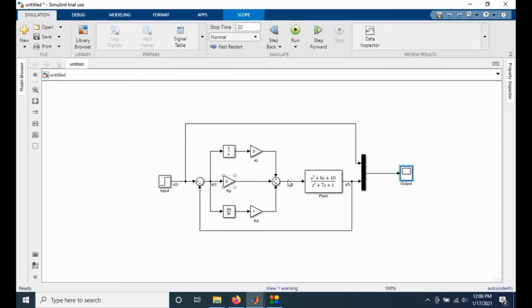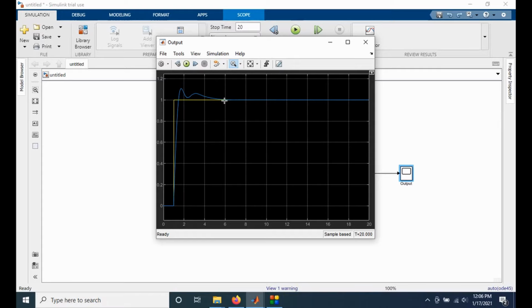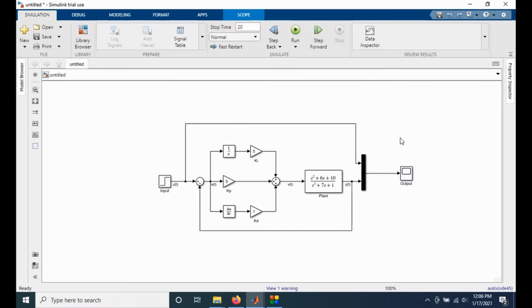We're going to deal with it in a slightly different way because it's related to the final step of controller design. At this point, we have tuned Kp, Ki, and Kd, and we have verified that our output is within some sufficient parameters. What we have not done yet is verified whether the input into the plant is achievable. Let's create a new scope and call it TF input. And we'll connect it right here.